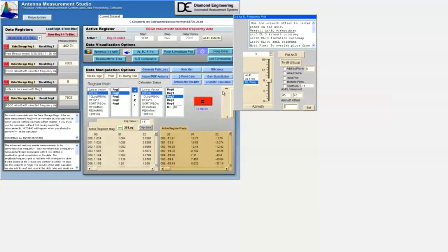There are other options such as multiple plots, holding plots, or adding a wireframe. The holding plots button allows you to superimpose many different plots over one another, allowing you to examine the different sizes and shapes. The azimuth offset option enables the shifting of the azimuth plot for antennas which are centered at about 0, where the plot does not have an end point.